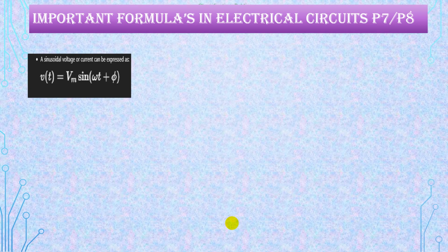For inductance, the current always lags. This means if the voltage starts at the 0 point, the current will start after 90 degrees. If it is pure inductance, it is exactly 90 degrees. Generally in the market, nothing is pure, right? Inductance will come with resistance, and capacitance will come with resistance. So the angle will change and 90 degrees will not be there. It may be 45 degrees, maybe 80 degrees, depending upon its purity. So the lagging is always there. The current always lags the voltage for the inductance.